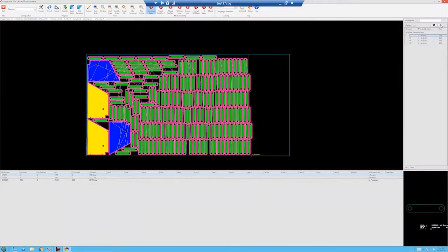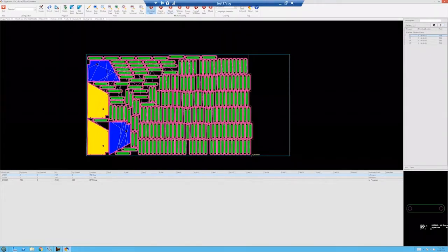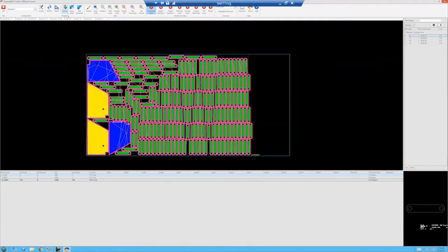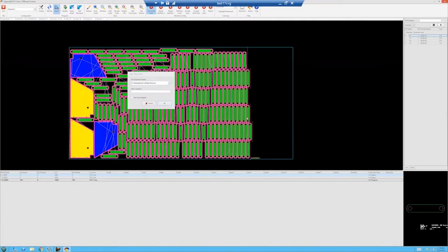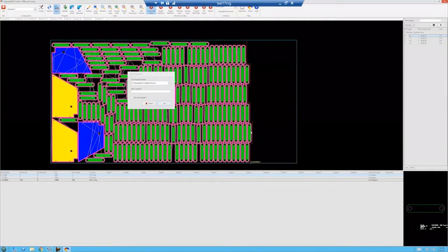And the nice thing about this tool is that you've got a time calculation tool, so you can start a ticker, which is going to calculate your real cut times. Go ahead and stop it. You've also got the ability to reject parts. So if I get to the very end of the cutting process and realize that one of my parts was scrapped for whatever reason might be, you can select Reject Part. Maybe it was damaged in the cutting process. You can select the part that was rejected.